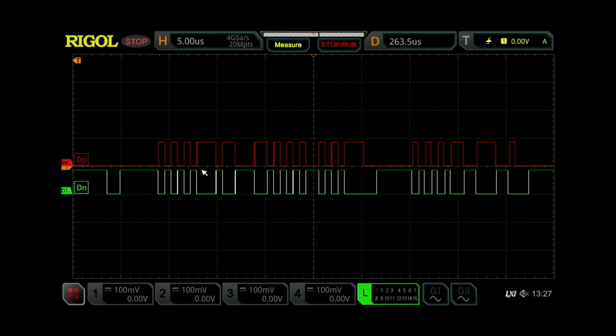And then there's the IN command, which comes up over here. And then there is an ID. Each device that is hooked up to a USB port gets an ID, but since there's only one host port on the ESP32, it always comes back with 1. You'll see that when we look at what these codes mean.